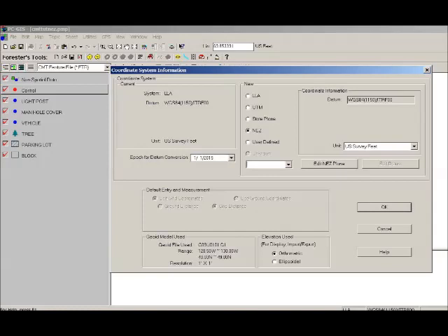Both the PC-GIS software and the ICMT-GIS Pro app provide a function to let you calibrate a local and easy coordinate system against 2 known points. You could use such a system to geo-reference a design drawing in a DXF file. You could also use it for doing stakeout work. If you have an accurate GPS receiver, you could use the GPS collect function to record points to use as the known points. These 2 points should be at diagonally opposite corners of the work site.